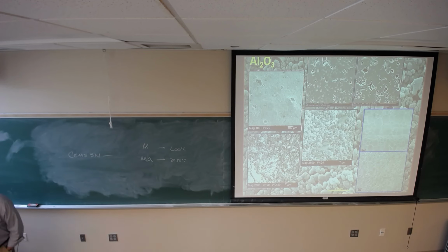Okay? These are hip replacement balls. This is zirconia. This one's great because it has a defect in it. You can actually feel it. Okay, and this one doesn't appear to have a defect. The zirconia thing is great. Okay, processing problems are pretty much exactly the same as they are for alumina in terms of getting it into this shape. Zirconia, though, because of its nature, allows you to polish to that surface finish. It's hard to do that with alumina for reasons I don't really understand. Okay, because I think you can do it with alumina.